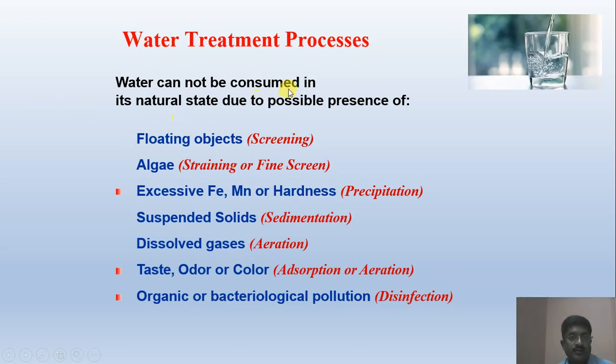Further, water cannot be consumed in a natural state due to the possible presence of floating objects. If the floating objects are there, we cannot consume it. The screening is necessary there. Algae, if present, straining or fine screens are provided.